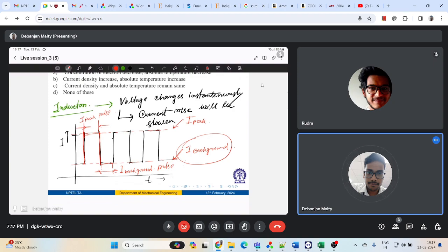So in a transistor power supply unit, it contains a transistor or solid state circuit power supply to regulate your output, or replace the reactors which are found in conventional systems, right? And this kind of power supply unit consists of a feedback system for regulating your welding parameters.